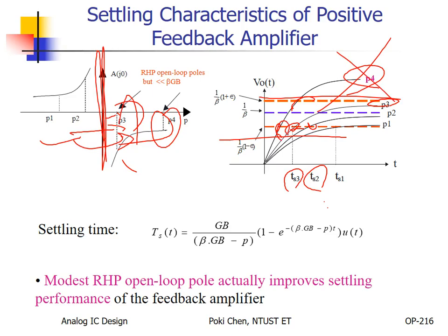Okay, so my recommendation is a little bit larger than 0. I mean, a little bit close to the boundary. Such kind of positive pole can enhance the gain and also the speed of operation of your op-amp. That's it. But not too much. Okay? Got it? That is the gift I got from Professor Geiger and passed to all you guys here. Hopefully, after this, you have new territory to design.